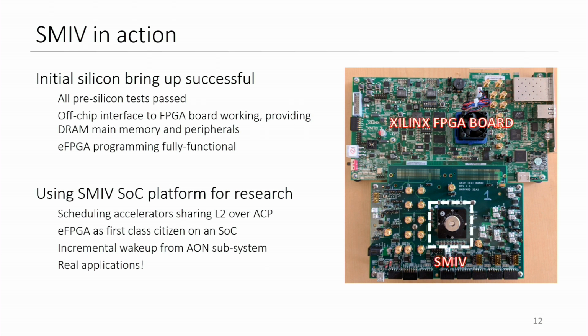Okay, so we have chips back from TSMC. There's a photograph here of our test setup in the lab. The board on the bottom is the actual SMIV test board with the chip inside the black socket. On the top is a Xilinx FPGA board, so we use this to provide a memory system with DRAM and also some other interfacing.